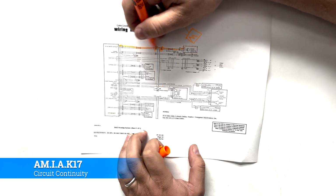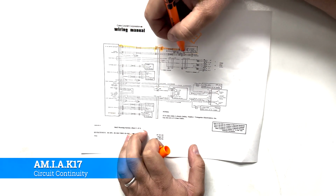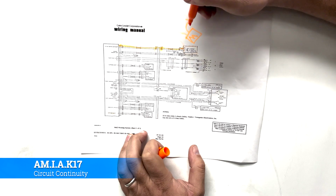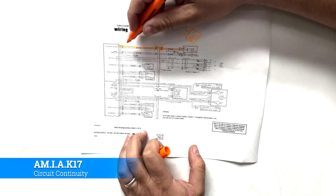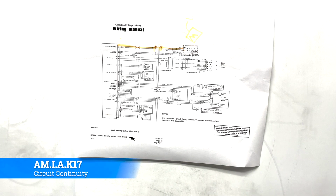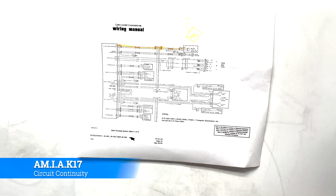And we want to highlight that just like we did, so that way we know that this one run is good. But now let's say we go to pin F and go to pin H, same thing, we just move this lead over and move this lead over, and we don't have continuity, then we found our problem. For whatever reason, this wire run right here is the problem. So we would then eventually have to access this area and shoot either direction to try to figure out where the breakdown is. But that's a simple example of how we would use continuity checks to troubleshoot. And you're going to do several of these whenever you get into class.